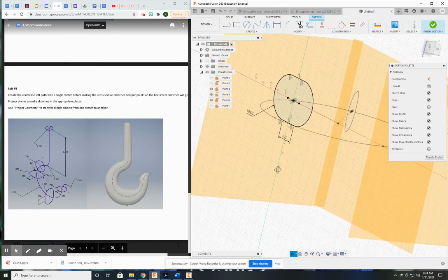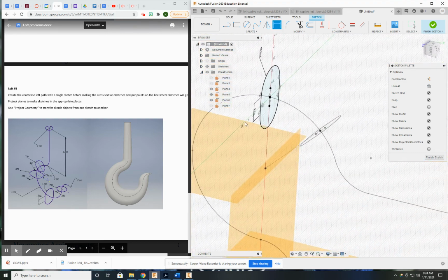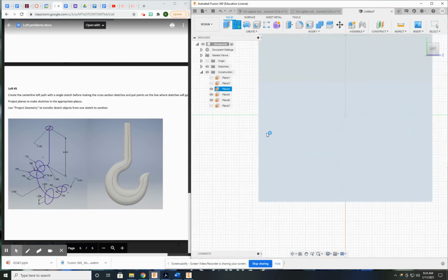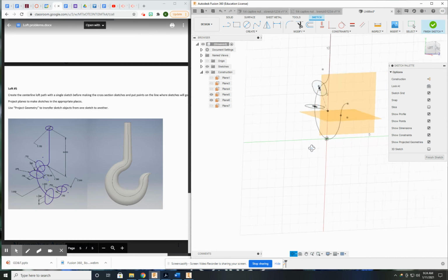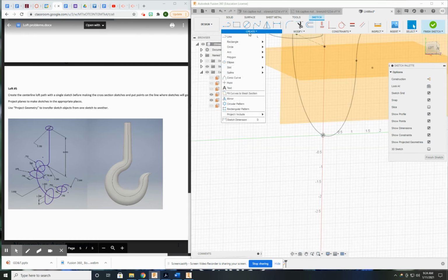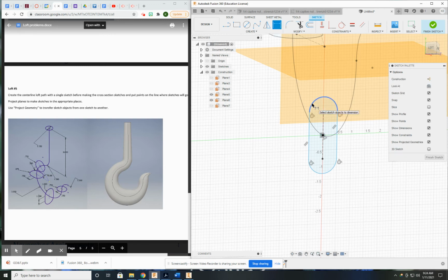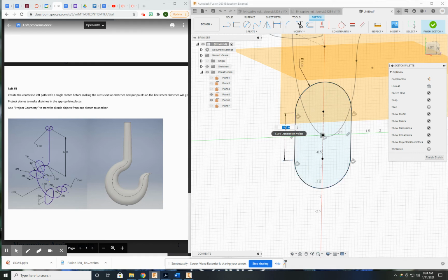It's going to be this guy down here, rotating all over. And this is going to be the bottom. Oh, lost me. Where'd it go? Okay. Center point slot yet again. Use that vertical line. By using the lines that are given, it's going to put the correct constraints in there to make less work for you. So when it wants to make less work and it does it in the correct way, let it.